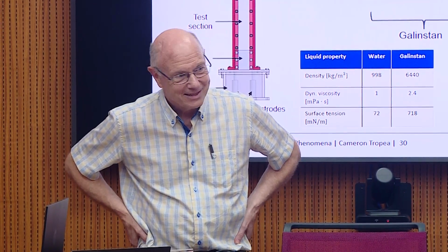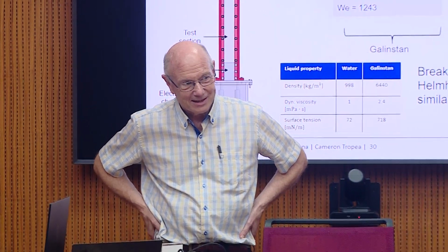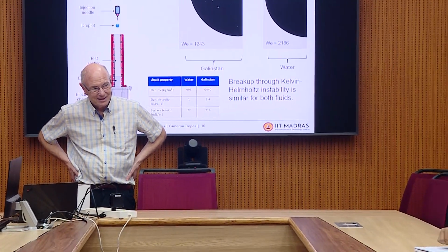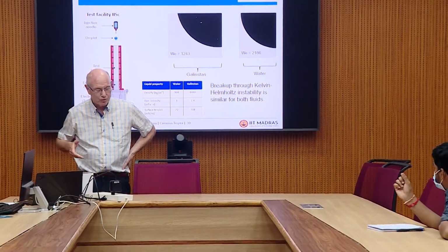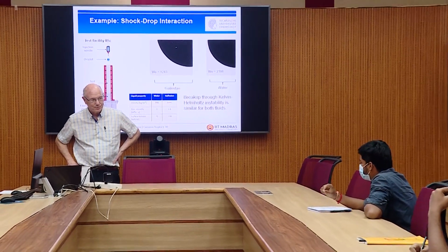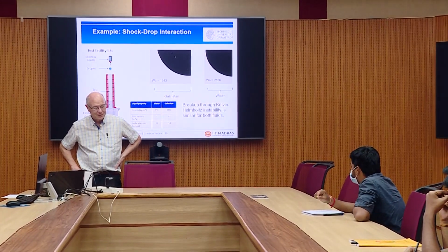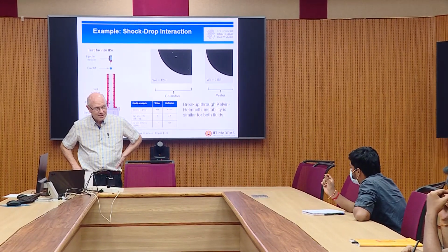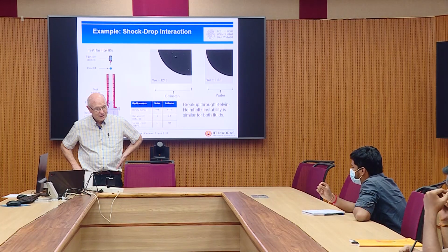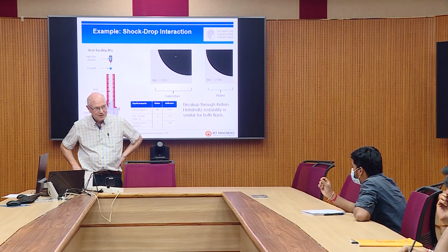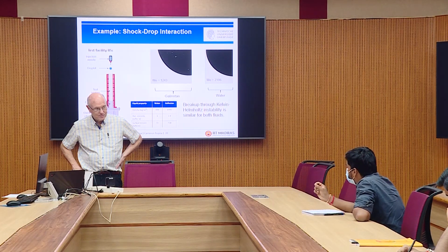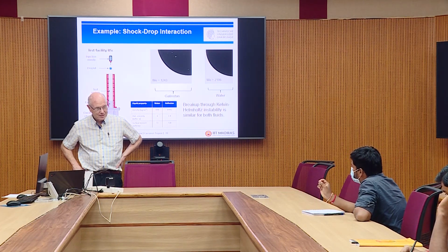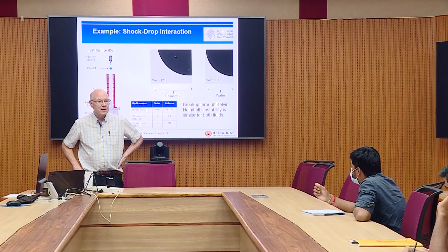One question regarding that ultrasonic atomizer, the droplet generator. You are giving an equation: diameter is equal to 2 times the hole size. But I have seen in literature, and we also have a droplet generator, that we get a droplet size similar to the hole. If we have a 0.2 mm diameter, the drop size we are getting is also similar to that. But you are giving it as twice the diameter of the hole size.